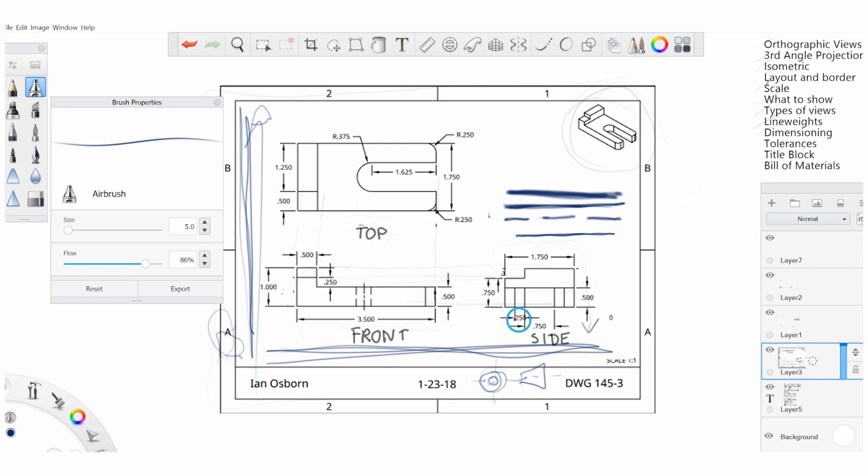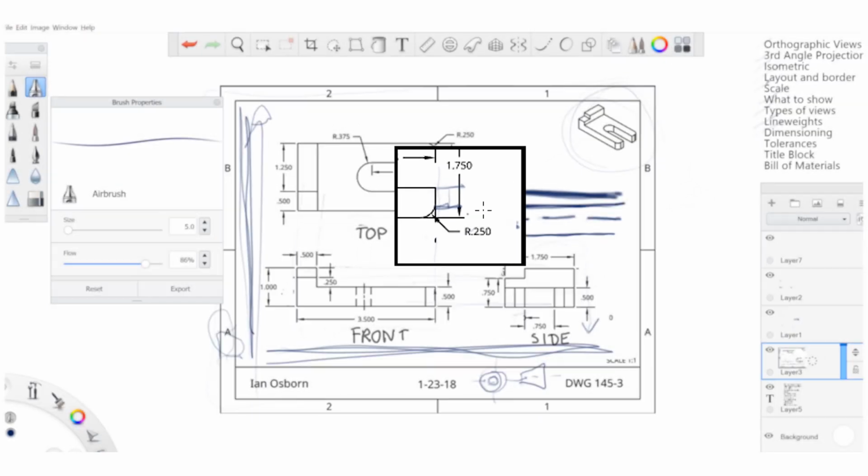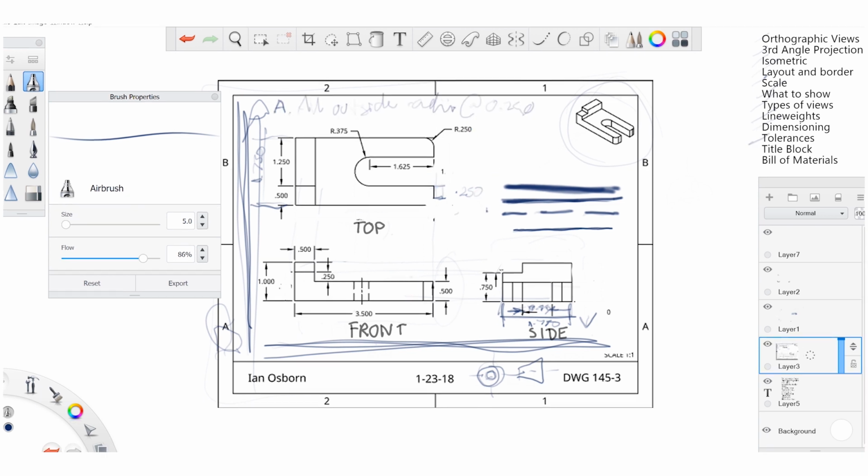And this 0.25 also irrelevant in that spot. It is far better over here because you can actually see what it is measuring. That measurement there is actually this flat surface before the radius starts. There we go, so as you can see that is far clearer. Okay, in terms of radii, we do have 2 radii here that are exactly identical. So we can actually get rid of one of these, and that is all for dimensioning.